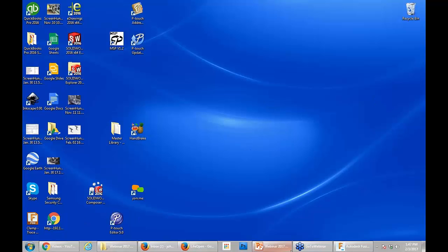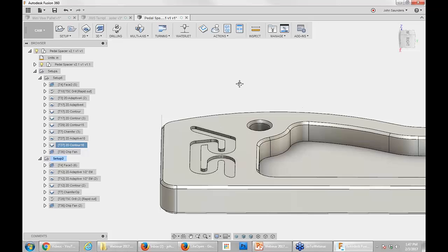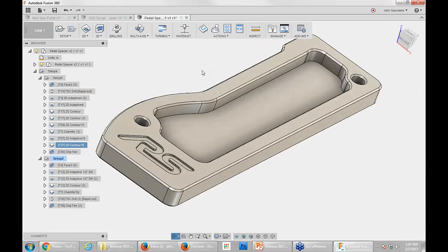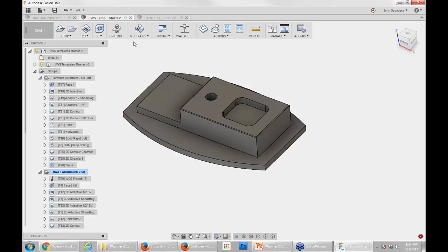Yeah, on the photo thing, you're right. There's a new G-code in the next gen Haas controls that allows you to call up the photo in the NC code. So we've actually got a next gen Haas post that will show the tool image. In the case of HSMWorks, where we set up sheet pictures, we'll show that. We'll continue to leverage this technology, but it's a great thing Haas is doing to move the ball forward and think about G-code as more than just instructions for the machine, but instructions for the operator too. Yeah, just how many times have I picked up a set of soft jaws and thought which one was in the fixed jaw, or just the confidence that you're using the right part is amazing.